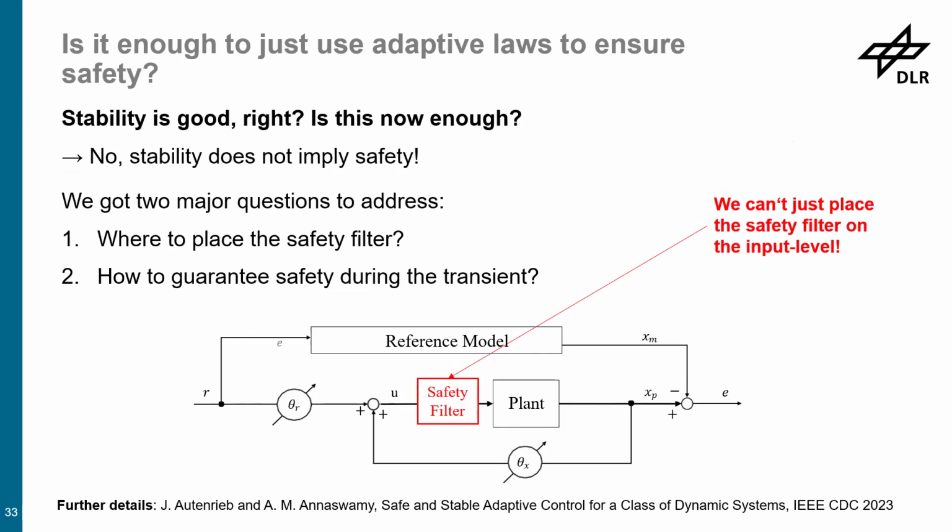It's interesting. The only thing I'm questioning myself is that we could have the issue of windup, right? It has to be addressed, because if we place it here, you will still have the problem that the reference model will try to converge the system towards R, right? R is still driving the reference model, then we have XM, and E is used for the adaptive flow.